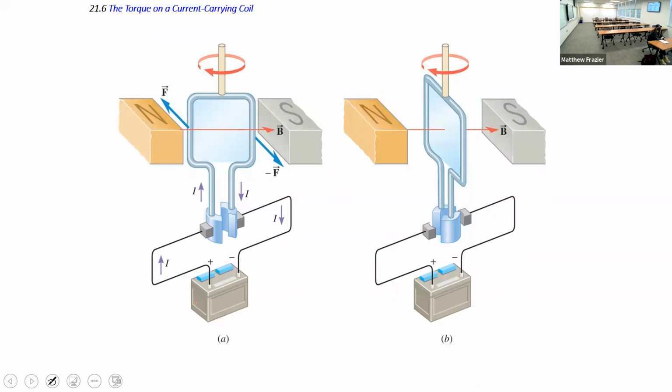So you hook a battery up to this. When it gets to one orientation, the current will always flow towards the north pole, then through the coil, and then from the south pole back to the brushes. And then when it rotates around to the point where there would be no torque, the current cuts off, and that allows the coil to coast. Once the current cuts back on, the side that would be the south pole wire has now rotated around to the north pole. So the coil always has the same orientation when the current flows.